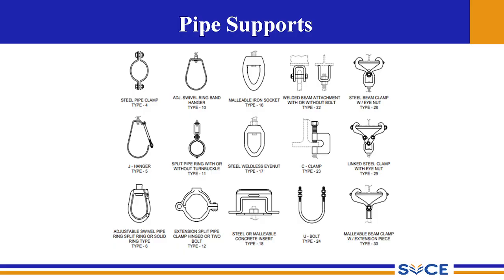So this is commonly used in pipeline supports in households also, which can support very small diameter pipelines. This U-bolt shaped rod with threaded ends can be used as a support or also as a guide. So if you have a U-bolt, we can allow the movement of the pipeline in a particular direction. This U-bolt type of support is normally used in the case of very small diameter pipelines. It cannot withstand heavy loads, so we normally use this U-bolt as a guide rather than a support.